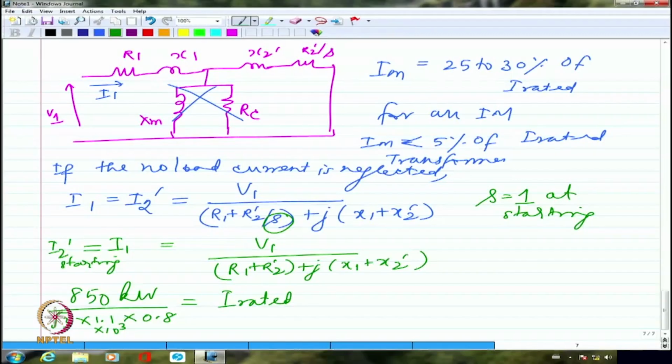So, I will not be able to start an induction motor which is rated for extremely large values without including a rotor resistance or without including any other starting means. Right? I have to include some kind of starting technique in my induction motor. Actually, the power system authorities generally put up a rule.